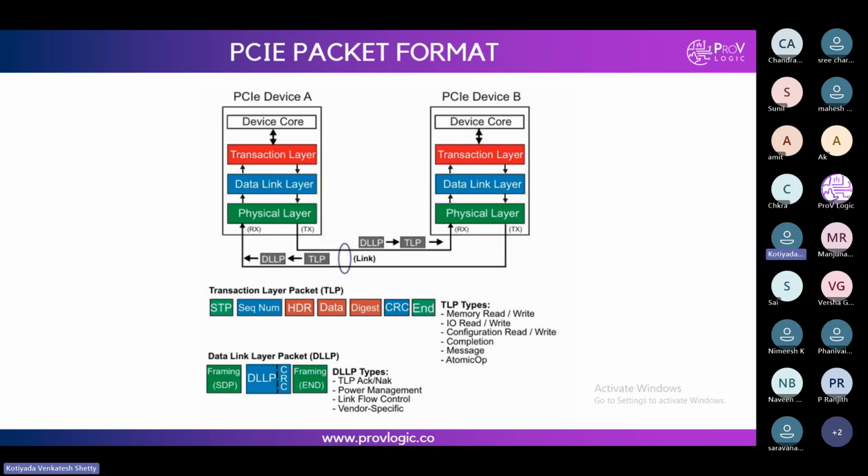In that memory space are your features and your configuration: whether you are native or legacy, and what transfers you support. Based on reading these, the host or other endpoint gets to know what the device can support and which transfers it can do. Did you get the point?